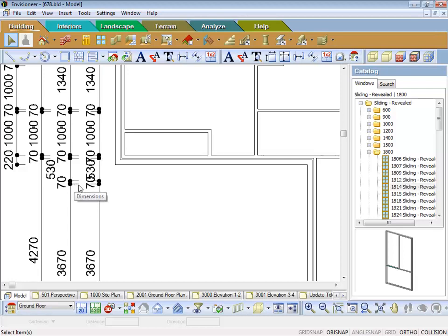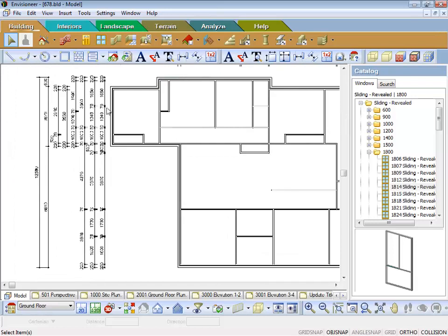Alright, now if I roll in close, see how top to bottom has put my extent lines pointing to the right. Now if I go bottom to top, you can see all my extent lines are going into the text. Now to me, that's a lot of tidying up to do. I know there's a number of people such as building designers and that are very fussy with their dimensions, but for me, I'm quite happy with that. I think that's a lot tidier and less tidying up to do than this one here. So if I just get rid of that.